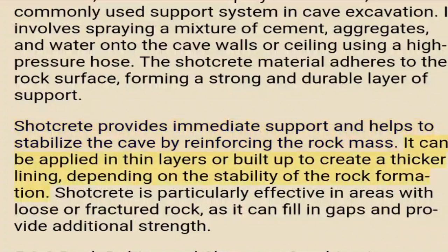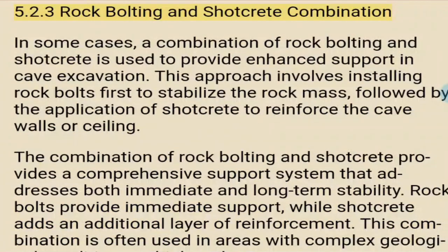It can be applied in thin layers or built up to create a thicker lining, depending on the stability of the rock formation. Shotcrete is particularly effective in areas with loose or fractured rock, as it can fill in gaps and provide additional strength. 5.2.3 Rock bolting and shotcrete combination.